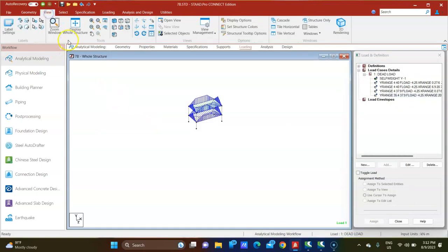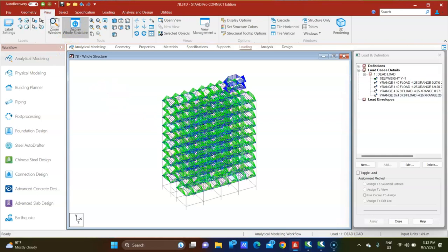fine. Now you see the all view, all the floor have been loaded. Live load also, same method, right? Sometimes for a particular tool, you will be using for toilet, you will be using for kitchen, you will be using for stove, for each case your live load is different, right? So if the live load is different, that is the way by which you can provide the zonal loads. And now tell me if you have got any questions.